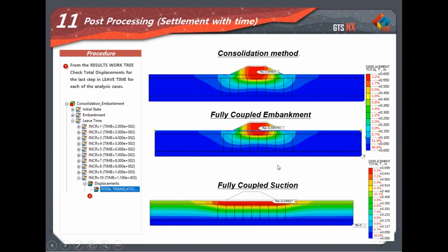But you can see how this can be considered a method of improving the soil beforehand, or some sort of special case that maybe the embankment, for this needed to happen before the embankment is constructed. The soil needed to be improved for some specific condition. You couldn't just go ahead and start the construction of your embankment. But in itself, we were also trying to recreate a similar distribution as what we saw for the embankment case.